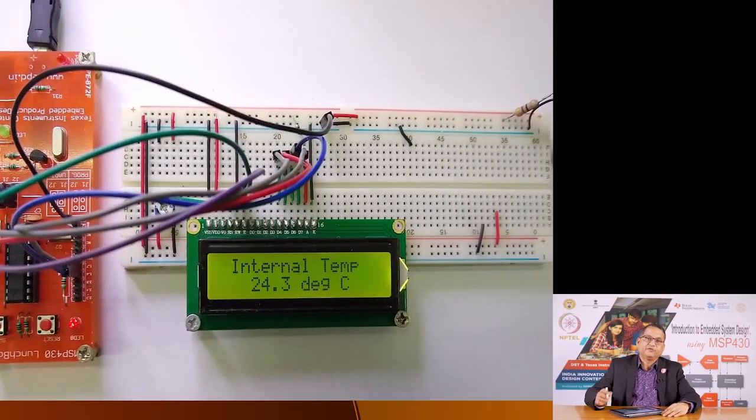These are the formulas that you have, and once you understand this code, build and download it into the MSP430 lunchbox, what you would see is that the display would tell you the temperature at which the MSP430 is currently operating, and you can see the impact of it by trying to cool it, or maybe you connect your soldering iron gently onto the MSP430 IC, and you should see this temperature reading changing.